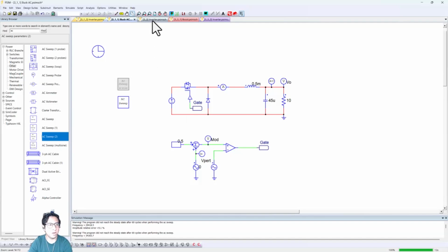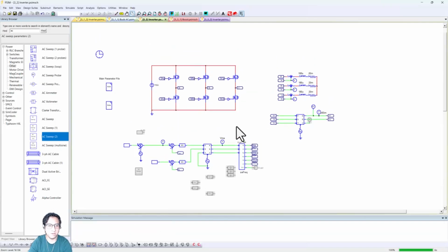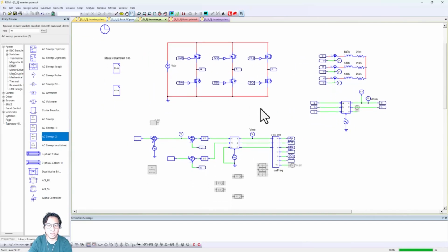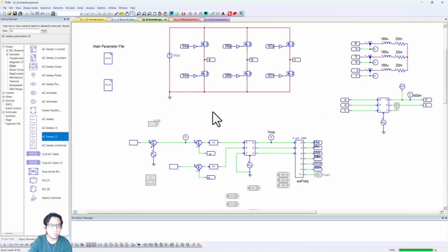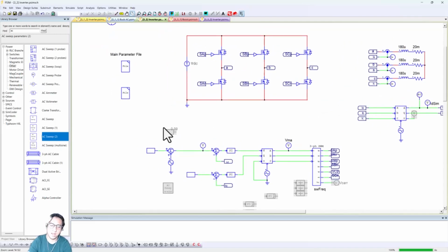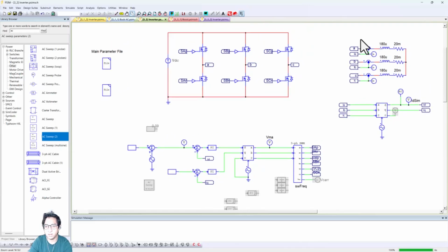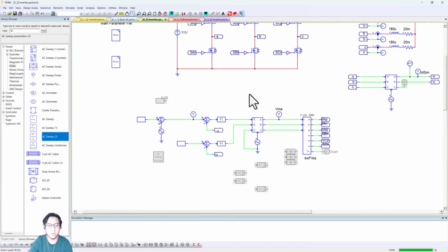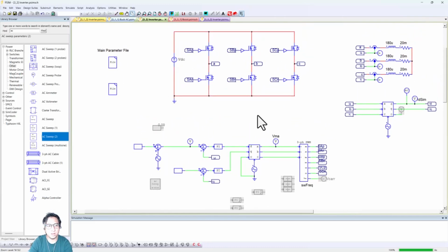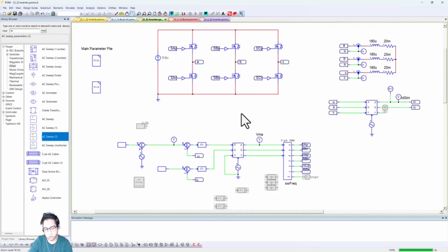We're going to look at controls issues, specifically what would happen when you digitize a controller. So here we have the same inverter as the last example, and I've designed a couple of controllers. This is current controlled. So I got, again, the measurements from the phase currents, got everything on the DQ frame and do DQ control. So what steps would I take to digitize this controller properly?